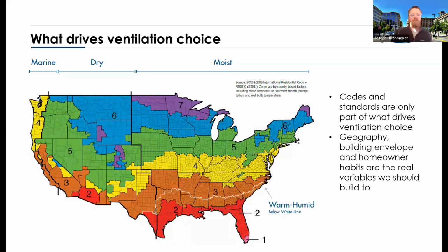So, it's extremely important. We've heard a lot about ventilation. Thankfully, during the pandemic, ventilation and air purity have definitely gotten some due press, but humidity is a part of it too. I don't think they quite have the studies yet to where they're comfortable saying humidity definitely lowers it by X amount, but we can talk in generalities about how we know viruses respond, and how especially airborne viruses respond to air that's well humidified. And it's that they're less infective. So, again, staying around that 50% mark, or a little bit lower in the winter, is going to help keep the family safer from that point of view.